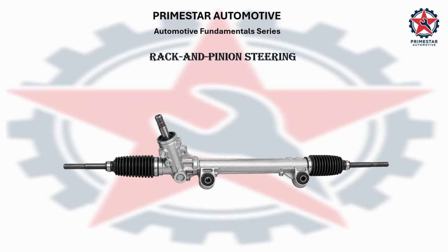Next is the rack and pinion steering system, or a conventional steering rack assembly. It is a mechanical linkage mechanism that converts the rotational movement of the steering wheel into the linear movement needed to turn the wheels of the vehicle.